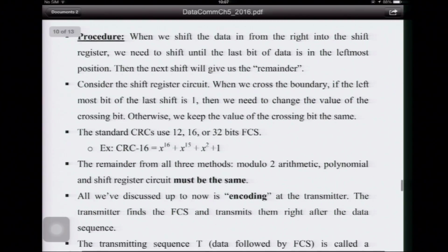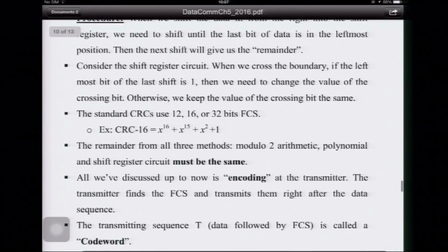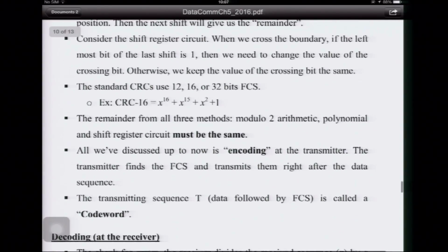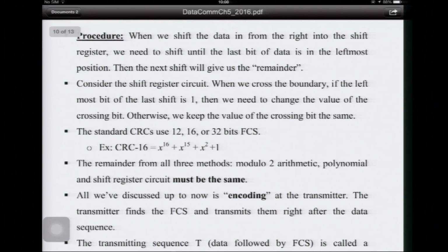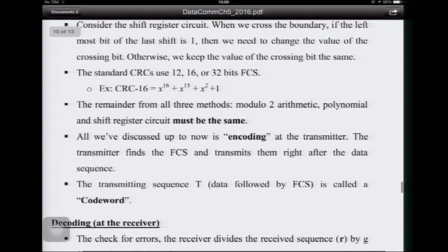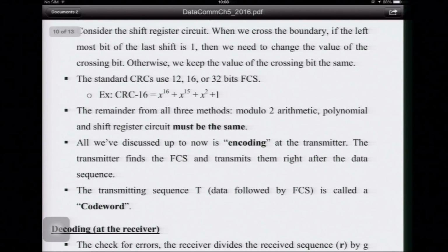Basically we will shift the data in until all of the data is inside of the circuit. So you don't have to worry about this. We shift the data in from the right and shift until all of the data is inside of the circuit. And then for the last bit of data coming in, you get the frame check sequence, or the parity check bits.